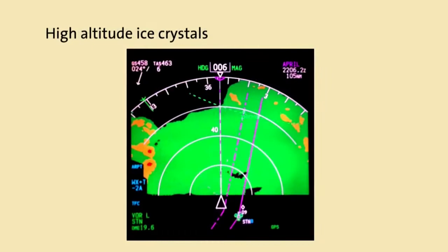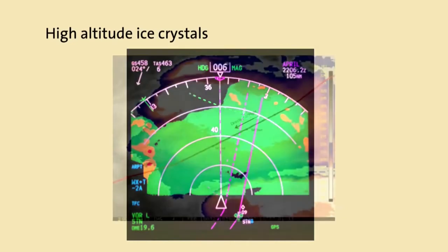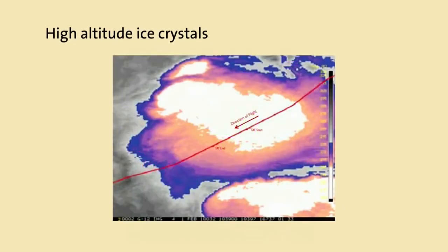During high-altitude operations, interpretation of this picture changes. In this case, a broad area of green may indicate high-altitude ice crystal conditions. As this satellite picture shows, ice crystals can be present over a broad geographic area. These ice crystal clouds have resulted in TAT anomalies and engine power loss. The new high bypass engines appear to be especially susceptible. In this case, the aircraft transiting the area experienced TAT anomalies about halfway through the ice crystal region, and the anomalies stopped shortly after exiting.